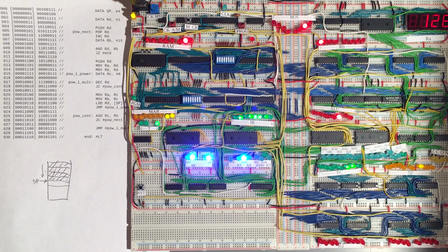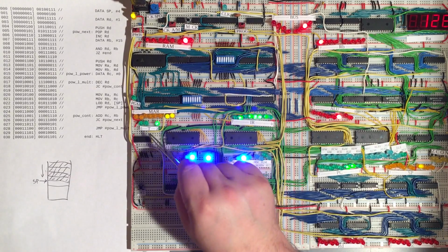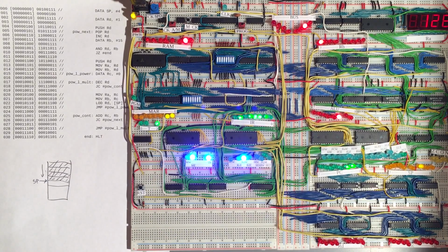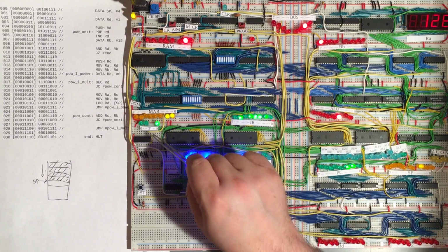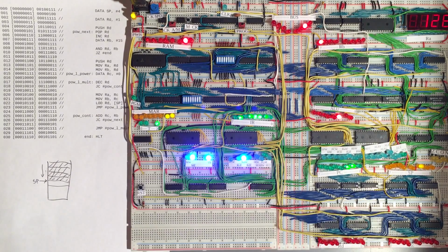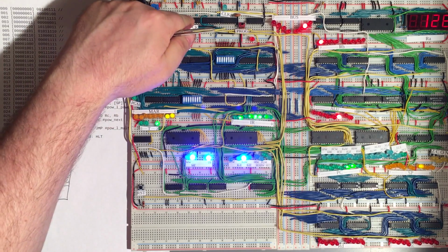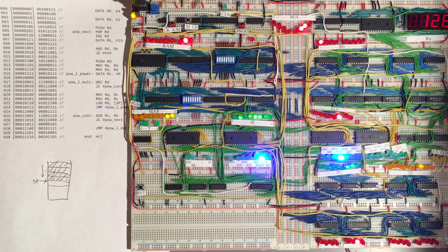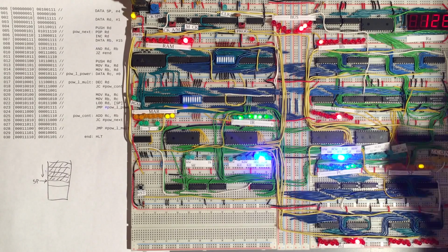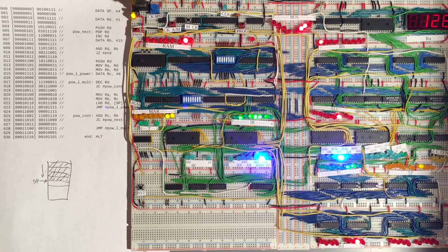And so in fact that took 3 cycles of our micro time, and so right now we're on time t4, but that will be the end. And so after that we will reset back to time t0, and we'll start executing the next instruction, which is this one. And so there we are. Now that 2, which is of course the base of the exponents we've been calculating so far, is back in the D register, and we're ready to start the next instruction.